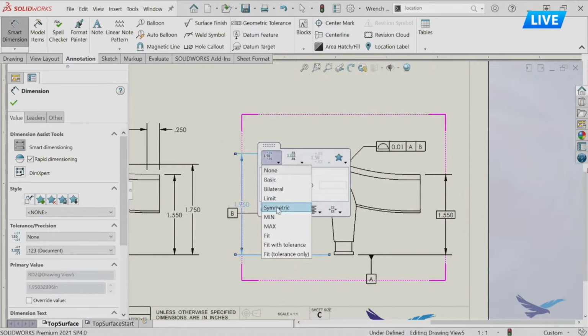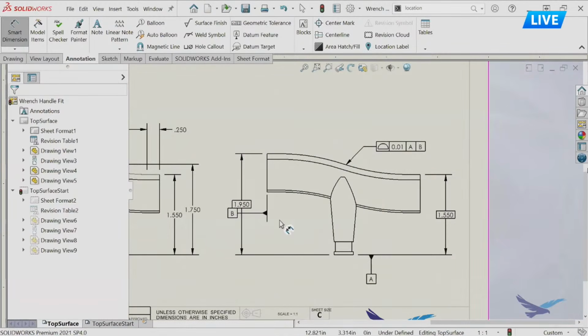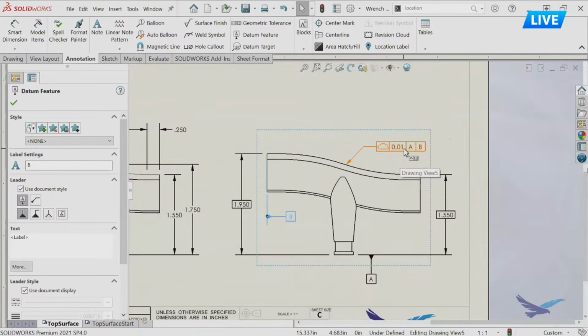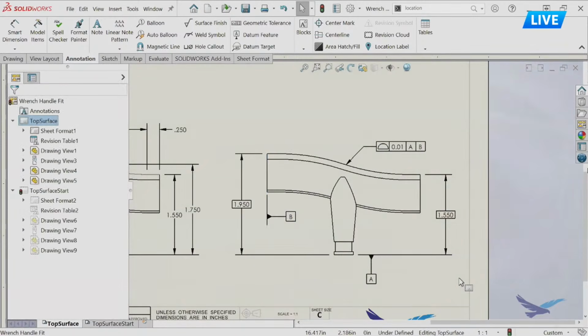It's basically this type of dimensioning, the profile of a surface should be referencing back to the CAD model. And for inspection purposes, you'd be using something like a CMM machine, digital off the CAD model. But these basic dimensions are still helpful for maybe a machinist choosing a piece of bar stock or something to be able to figure out what we need to cut this part out of.